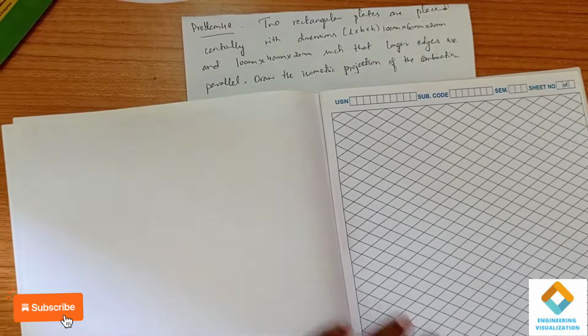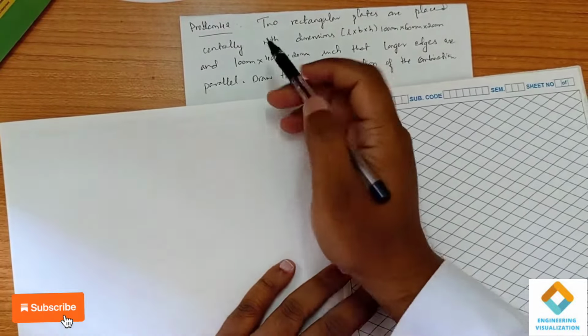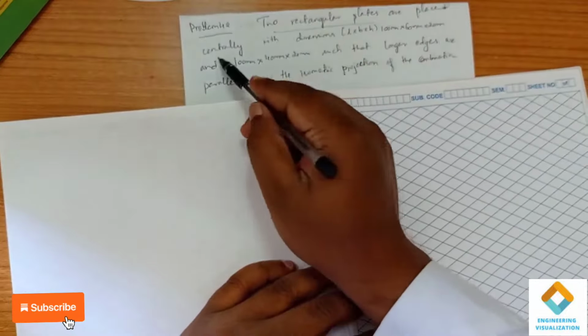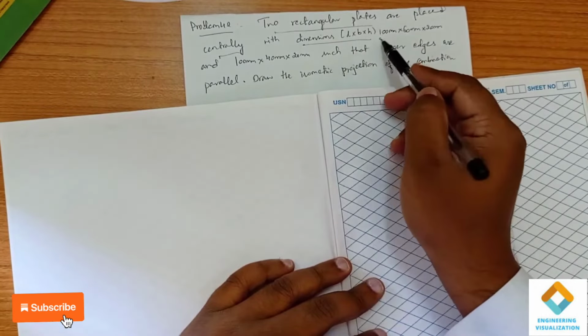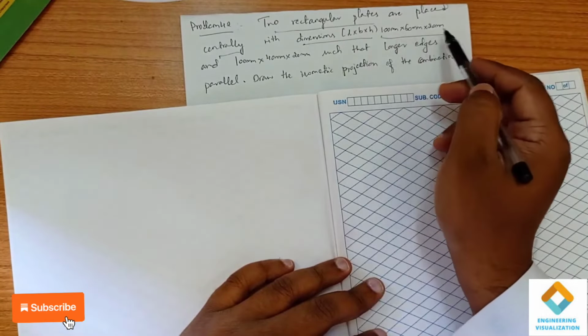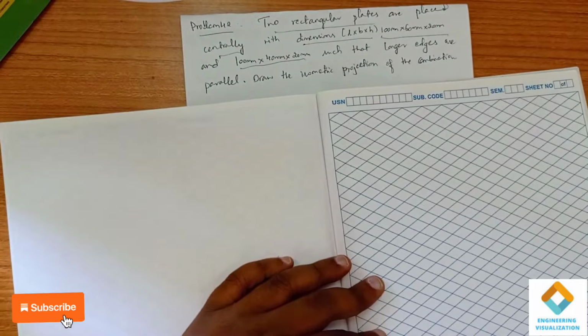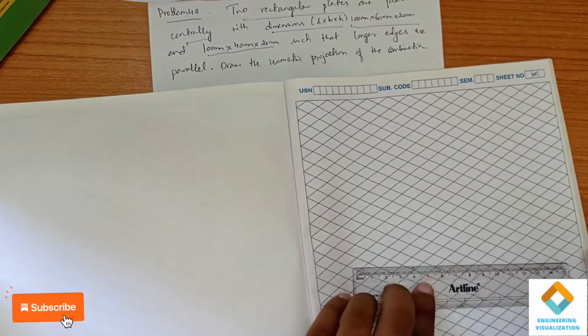Okay, we do another problem in it. Okay, it is problem number 42 from the CAD solution book. Herein we have to construct two rectangle plates placed centrally over it. One will have dimension L into B into H, length into breadth into height. So one rectangle of 100 into 60 into 20, another of 100 into 40 into 25. So first I'm going to construct here.